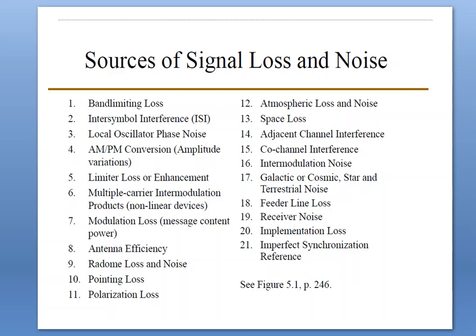And coming to the next one, adjacent channel interference. The interference is characterized by unwanted signals from other frequency channels spilling over or injecting energy into the channel of interest. How close the channels can be located in frequency is determined by the modulation spectral roll-off, the width and the shape of the main spectral lobe.